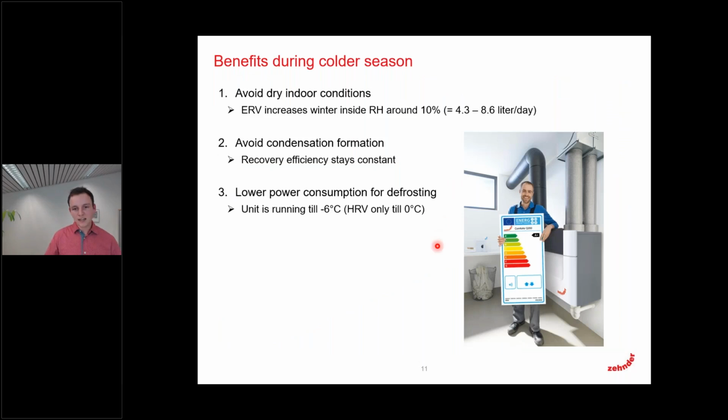So let's gather all the benefits, firstly during the colder season. First, I would like to point out the main advantage, and this is that we can provide with an enthalpy exchanger a very comfortable indoor climate because we avoid dry indoor conditions in winter. The ERV increases the inside relative humidity by roughly 10%.